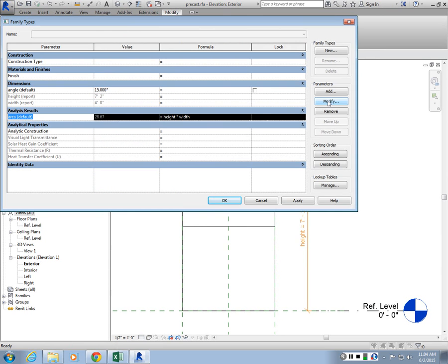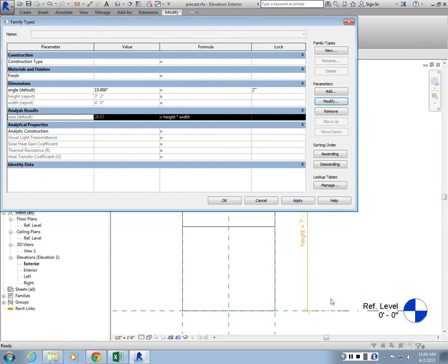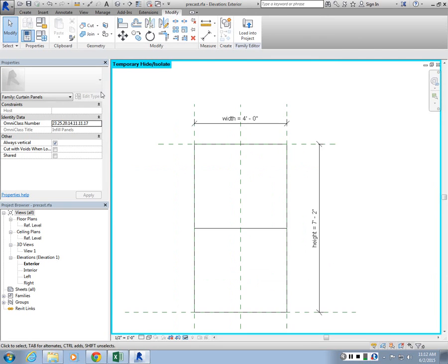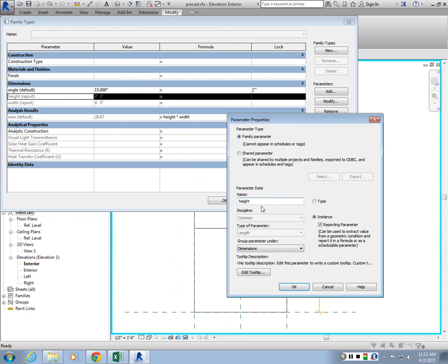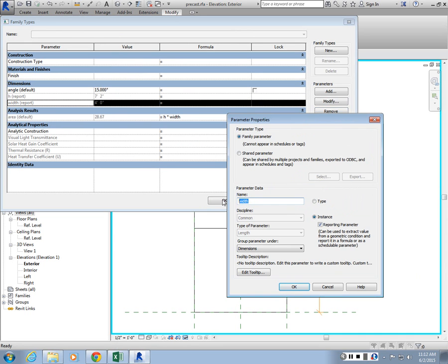Did you do this as an instance parameter? Is this an instance parameter? Is this an area? Alright, make sure that you dimension the planes for the parameters. And for practical reasons, you could also make your parameters into single letters, so they are easier to formulate and use.